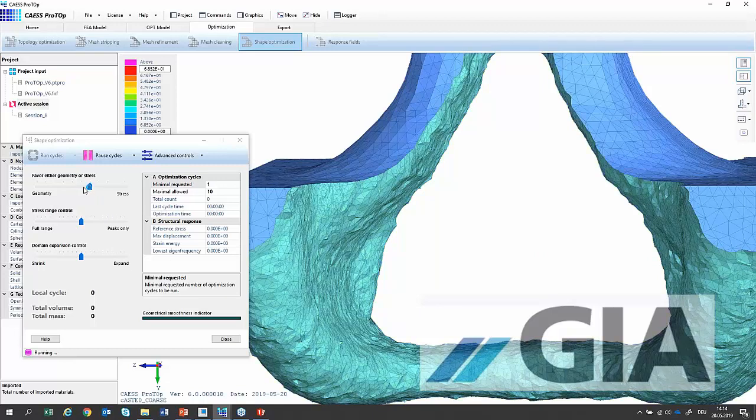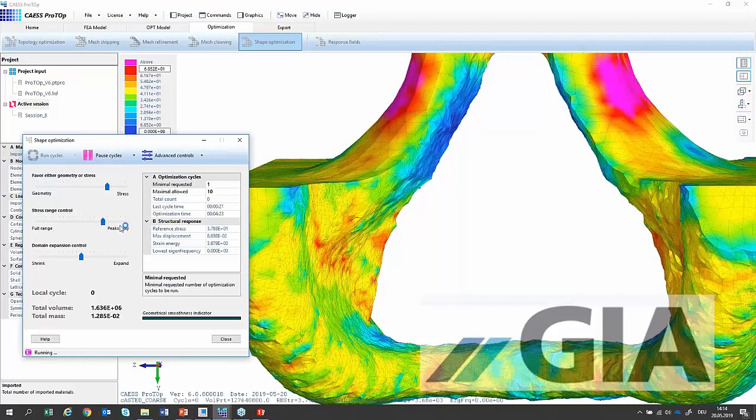And it also keeps an eye on the stresses and on the geometry. So it's not topology optimization we are doing right now. We are just moving the nodes a little bit in order to get a better stress distribution. And this will smooth the surfaces dramatically.